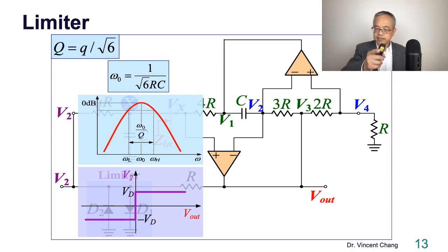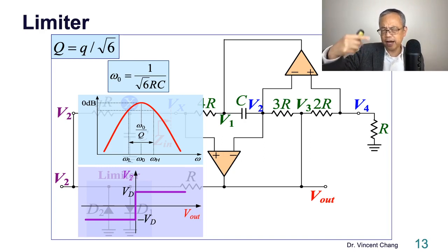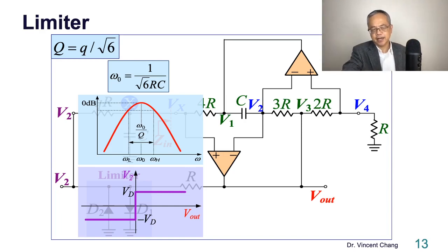Of course, this is the ideal. It's kind of ideal with respect to the V out. Because in reality, there's going to be a dead band concerning the turn-on voltage of the diode. Okay? So let's try to simplify these matters and ignore the dead band.